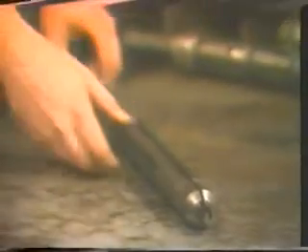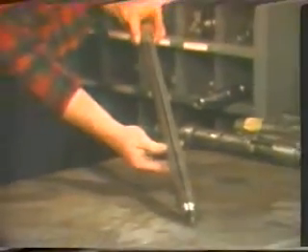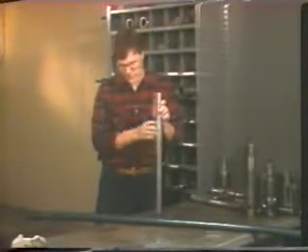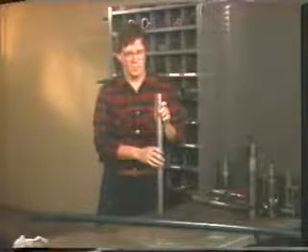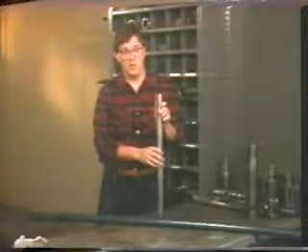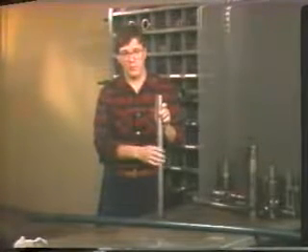The Kinley snapper is another tool designed to cut the wire line at the wire line socket. The assembly is allowed to fall into the well pinned to the wire line, and when the snapper strikes the wire line socket, the crimper and knife force the slipper to move sideways in the tool, cutting the wire line between the slipper and the knife. This action also crimps the wire line between the crimper and the slipper, which allows the snapper to be retrieved with the wire line. Like the cutter bar, the snapper must have a solid base upon which to work to cut the wire line. If there's any doubt that it will be able to reach the wire line socket, a Go Devil may be dropped ahead of it in order to give it that solid base.